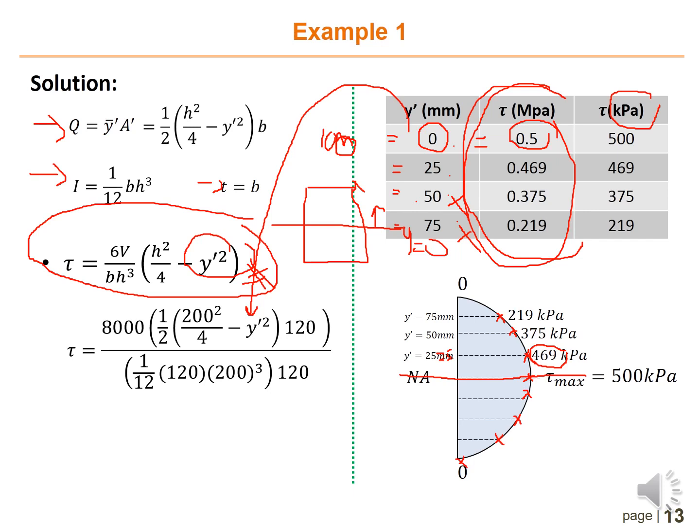So basically, for the shear stress, we have a parabolic arc. This parabolic arc is 0 at the top and bottom surface of the beam, and the maximum value is at the neutral axis.